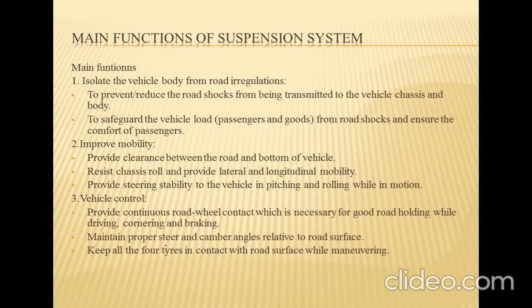We will discuss some of the main functions of the suspension system. The first main function is to isolate the vehicle body from road irregularities, in which the main objective is to prevent or reduce road shocks from being transmitted to the vehicle chassis and body.